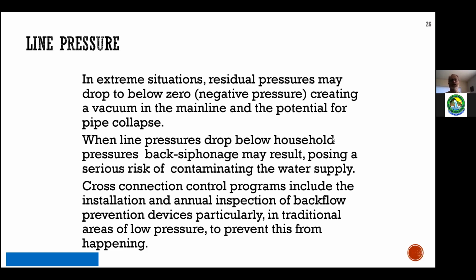the hydraulic configurations of our system, and that static pressure, static head. Once we start moving that water through the system, there's no longer sufficient energy in the system for these reasons that we talked about: the pipe being corroded, the pipe being too small, a valve being left shut or broken shut or throttled. All of these reasons can create excessive head loss that can lead to a negative pressure situation.